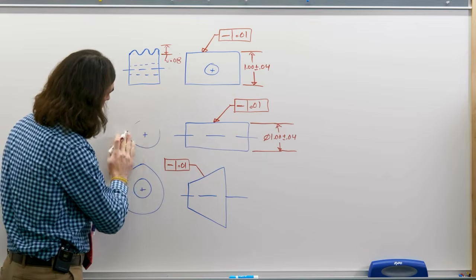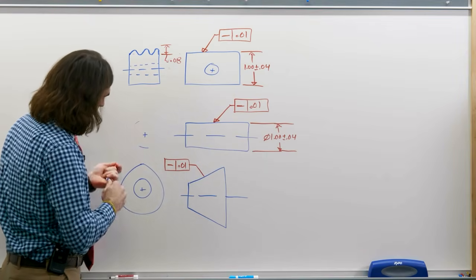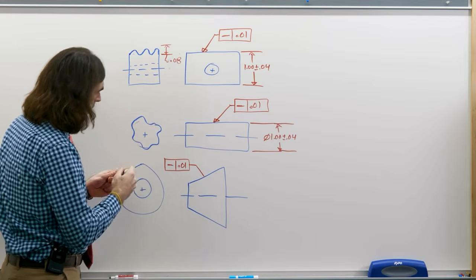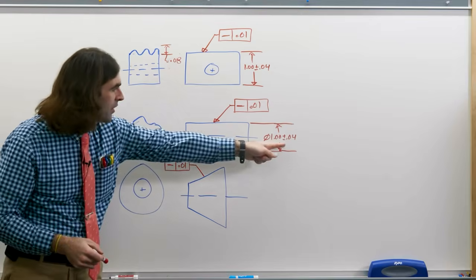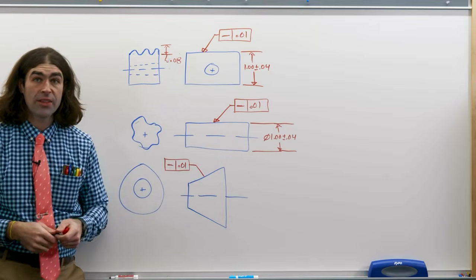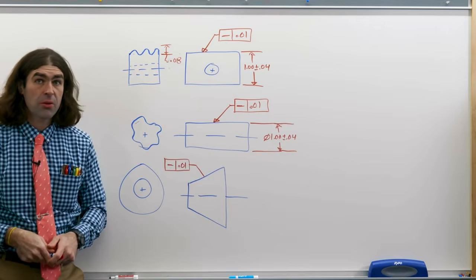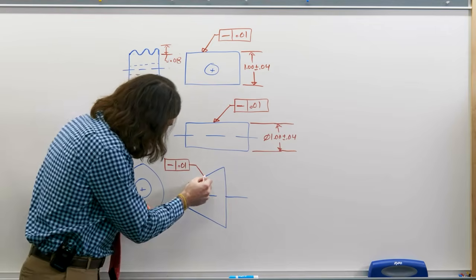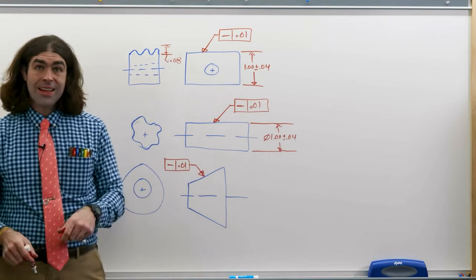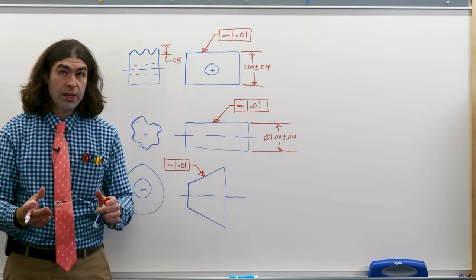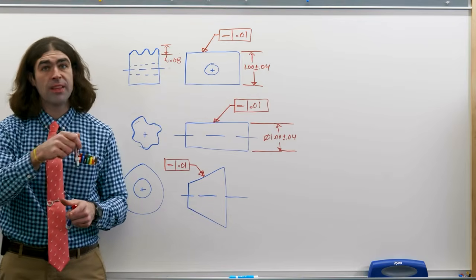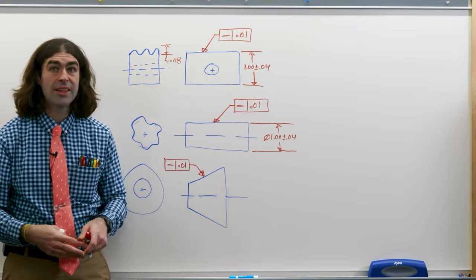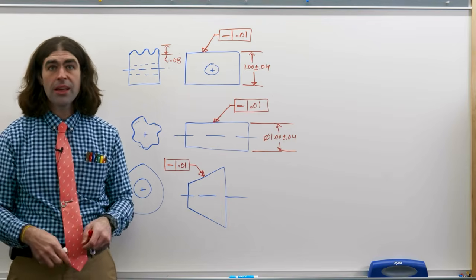So you could end up with a part like this if it uses its full size tolerance in manufacturing, okay? Next up, it can also apply to conical features. And in this case, inspection-wise, you'd put it on a sine bar in a V block and then just run an indicator across to see if each individual line element is, in fact, straight, okay?